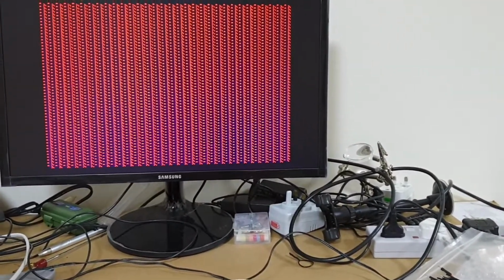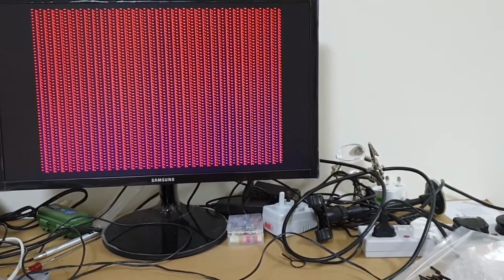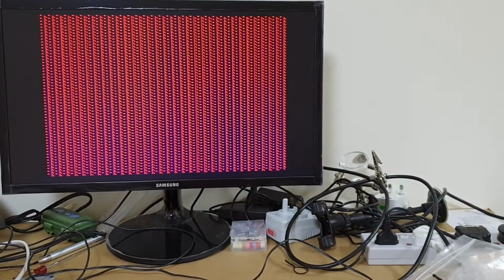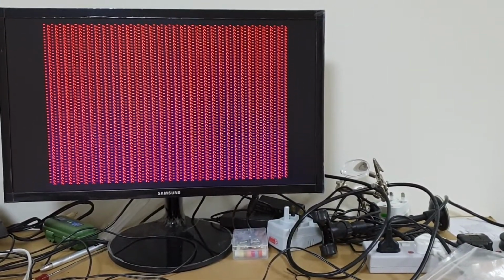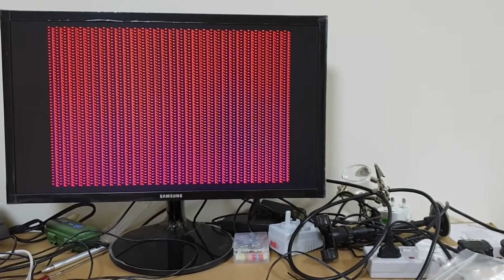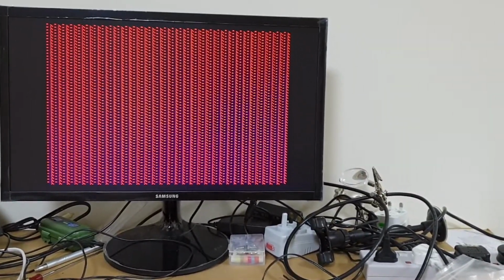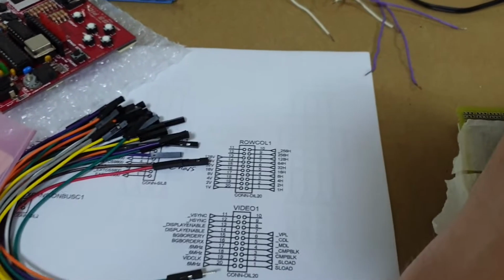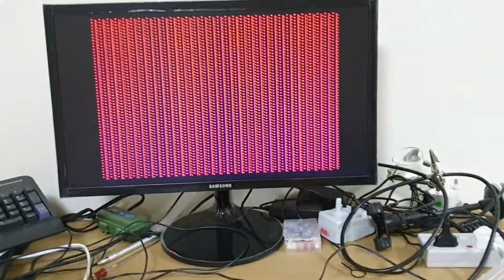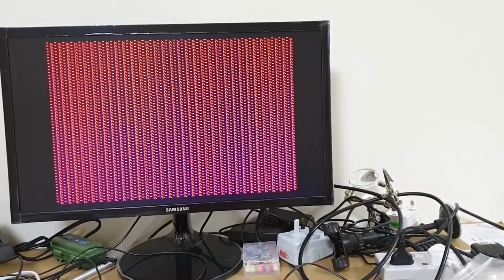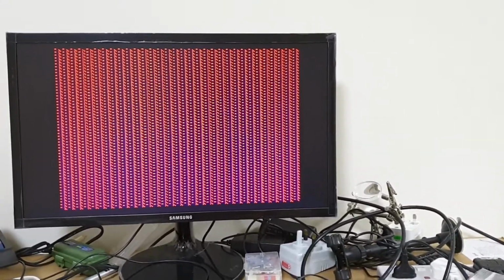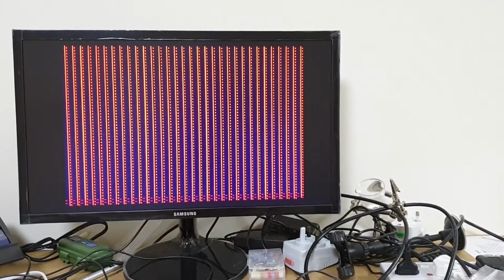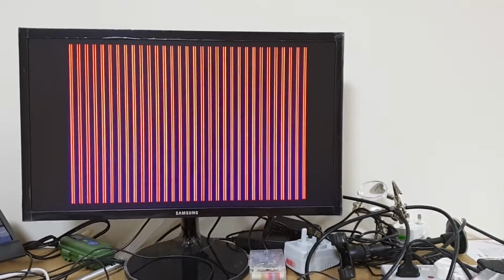So what does this tell us? Well, it tells us that, maddeningly enough, for the higher frequency pixel positions, horizontally or vertically, it seems that the lower portions, the signals towards the low end with the long cable, it's the cable length. So we can see here that I'm starting to get a repeating pattern of 4 pixels again, as expected. I engage more lines and I get more character positions, and then the screen flips out. So it looks like it's entirely down to cable length.